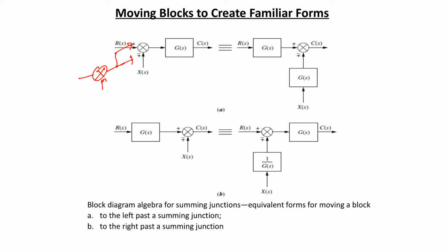It would not be possible to obtain the transfer function directly, because the pick-off point is there after the summing point. The signal would disappear if we converted this into one transfer function.